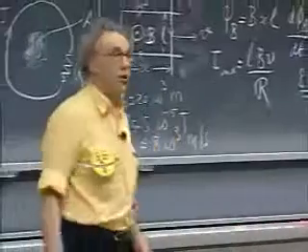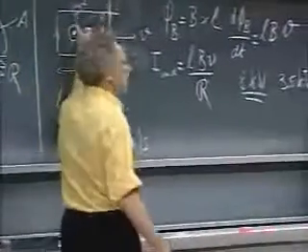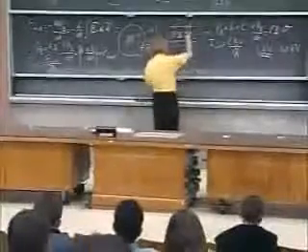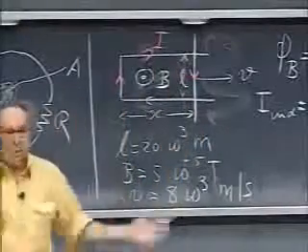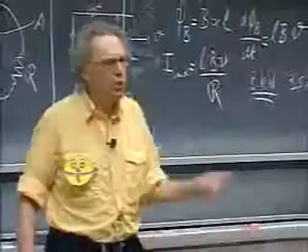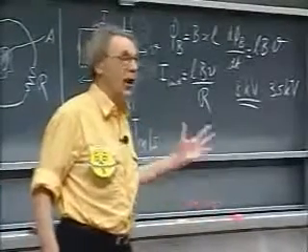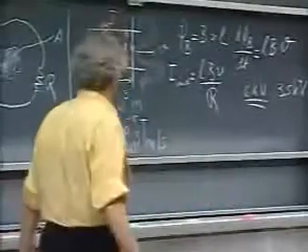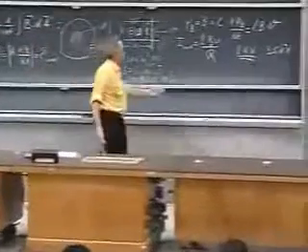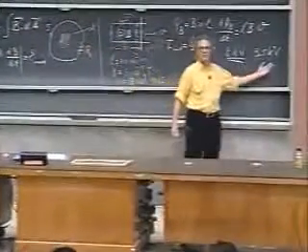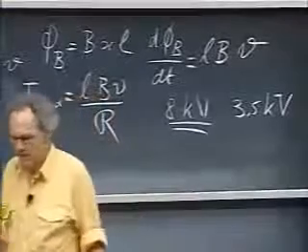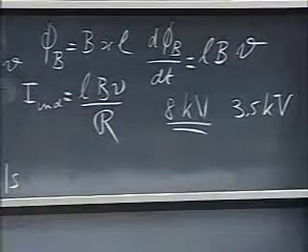And so, in the surrounding of this wire, here and here, you have a conducting medium. And so currents can flow through that medium this way or this way, and that's exactly what will happen, so that you don't know precisely the path currents will flow. So you do have closed loops. And so it is meaningful to talk about magnetic flux change and about the EMF, the induced EMF that is generated as a result of that.